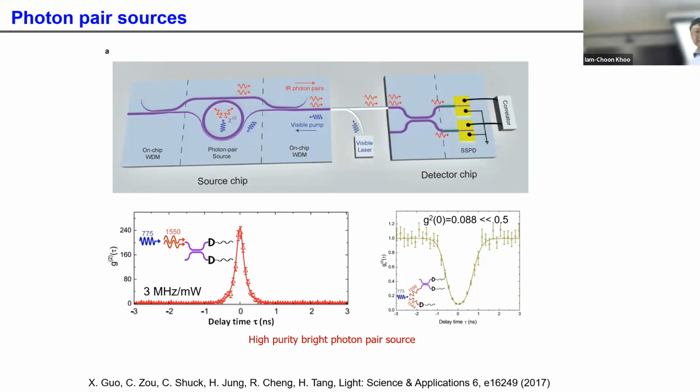Okay, so this basically addresses the question: how do you generate an entangled photon pair on a chip? Use this nonlinear resonator with a bulk inversion-symmetry-broken material. In this case, when I generate this device, you can also use lithium niobate. We always find that aluminum nitride can take much more power than lithium niobate. That's the advantage.